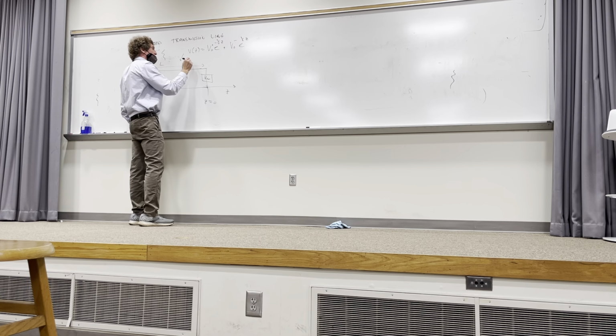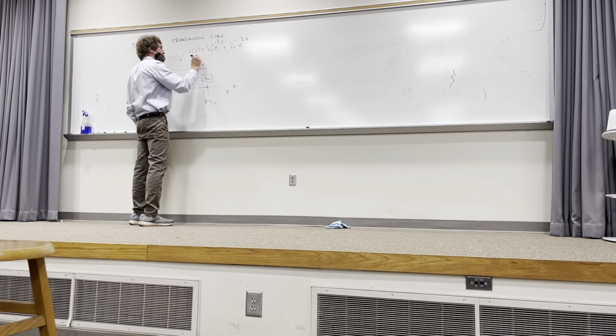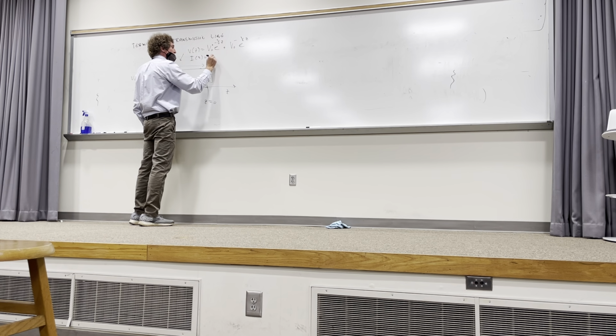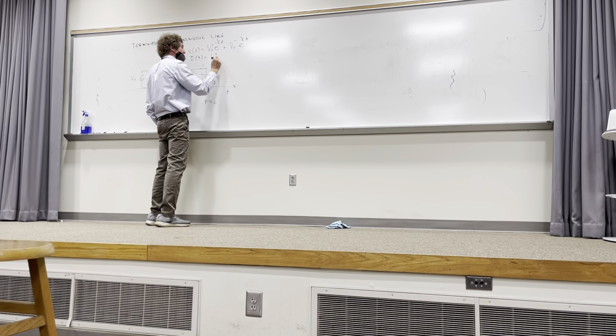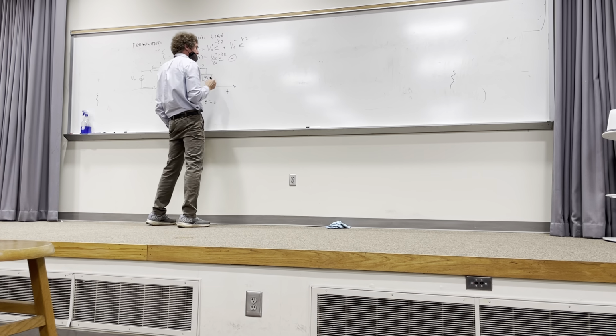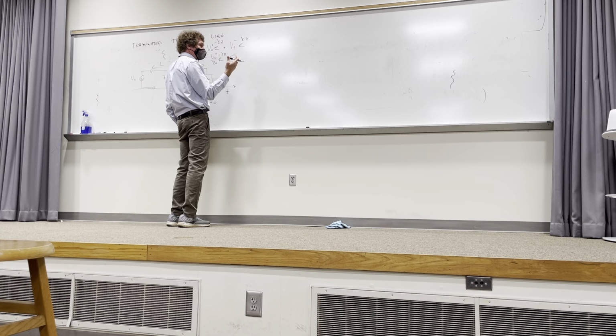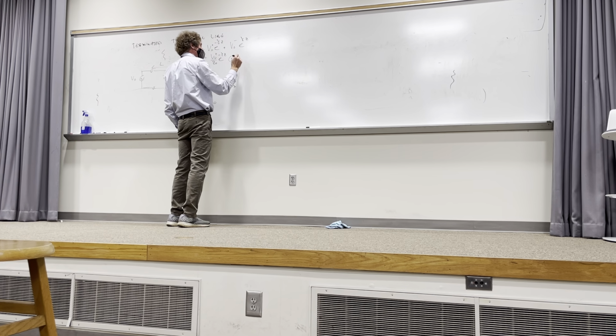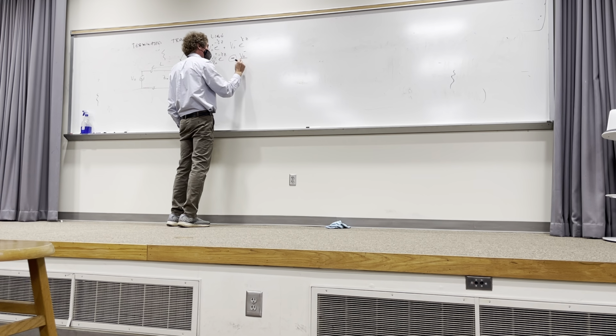And likewise, the current on that line at any point Z will be V0 plus over Z naught times e to the minus gamma Z. But this point is a minus. It's important you underscore that. It's because of the relationship of V0 minus to I0 minus. There's a minus sign there, and then it's V0 minus over Z0, and it's e to the gamma Z.